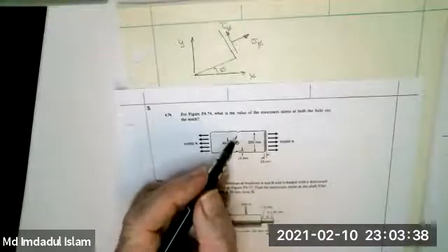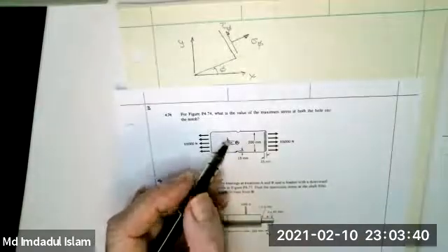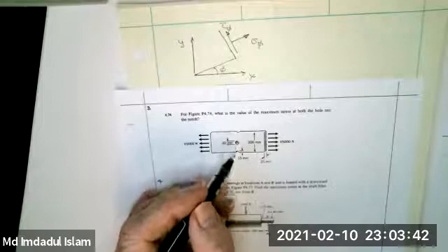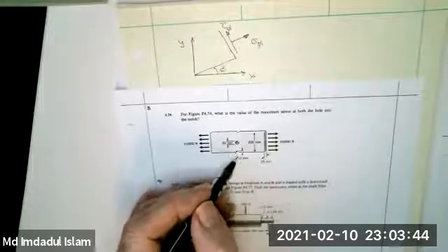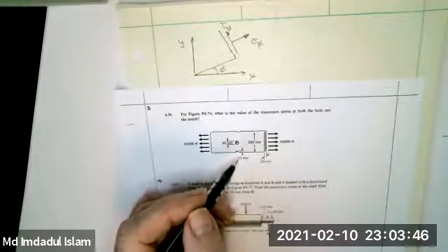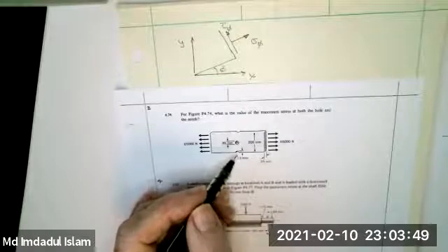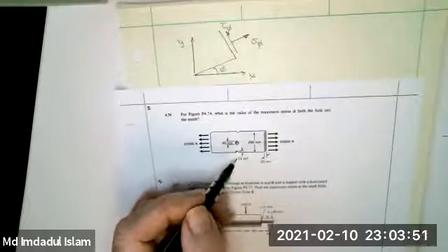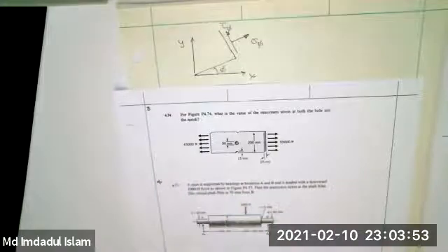There is a little bit of a possible interaction here between this notch, almost invisible there, and the other notch. They're about 3 plus diameters apart, center to center. There'd be very little interaction. But whatever interaction there is would increase the stress concentration. So it's a little non-conservative.